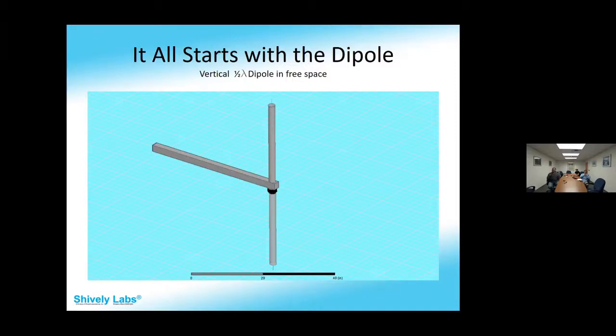If you reference to the isotropic radiator, you're going to have the one value reference to that, so dBi. Or if you're reference to gain in the dipole, it's going to be dBd, which is 2.14 or 15, depending on who you talk with, higher than the isotropic. So just starting a little background here.